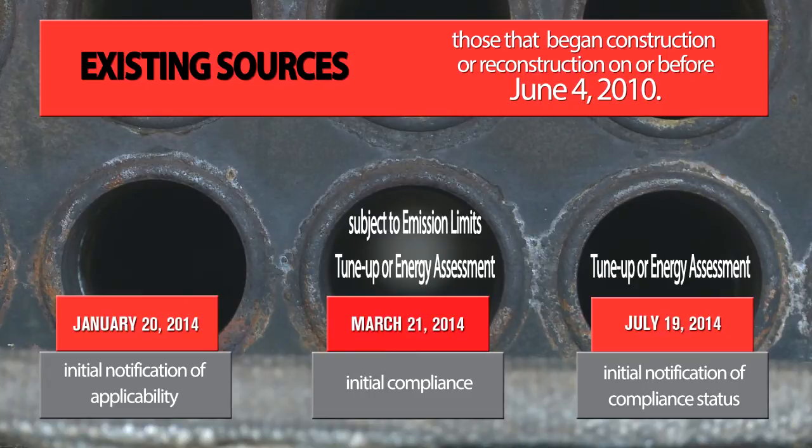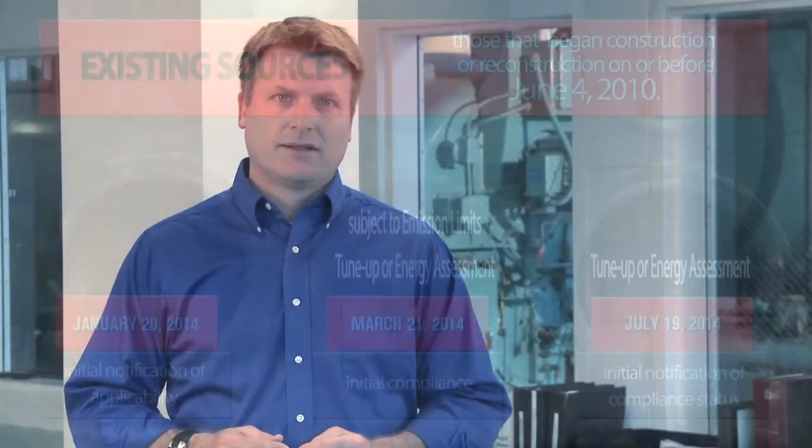Sources subject to an emission limit must comply by March 21st, 2014. For sources that conduct a performance stack test, you have an additional 180 days to demonstrate initial compliance with the applicable emission limits. Initial notification of compliance status is then due within 60 days of conducting the performance stack test.